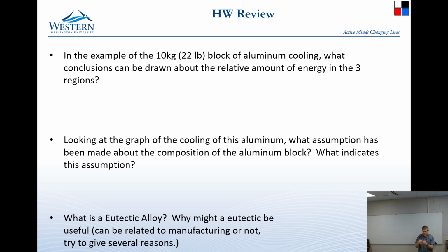That is the back side of those radiating fins, because they're cold, because they're radiating. The material will get there, and it will solidify, or not solidify, it will form into liquid, and as it does that, it will release this tremendous amount of heat into those radiator fins, and then it flows back through the wick to the other side.